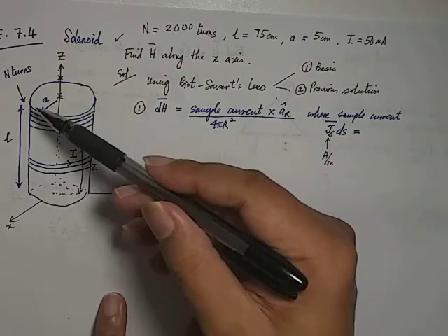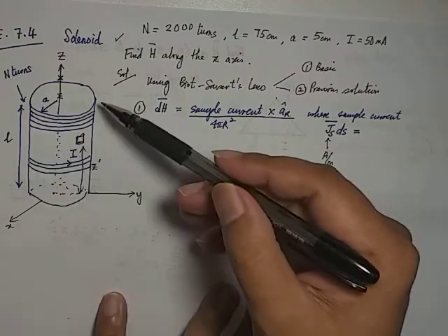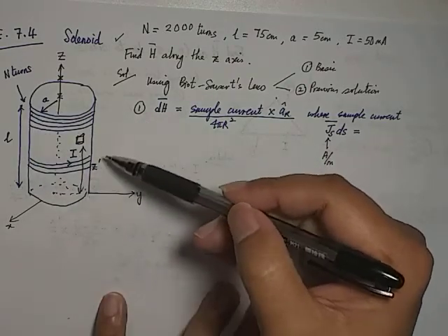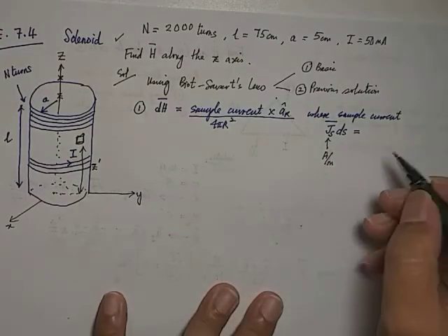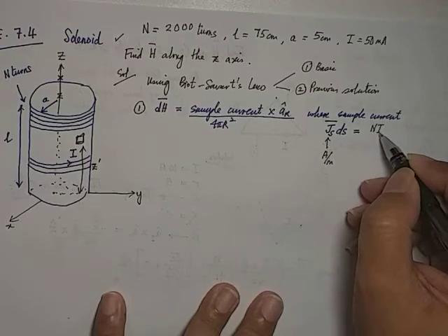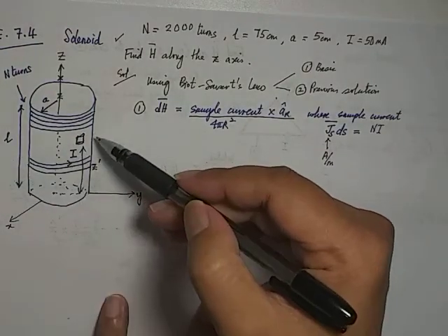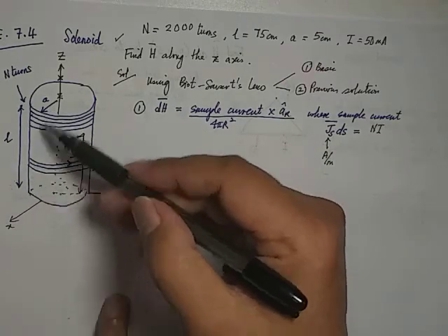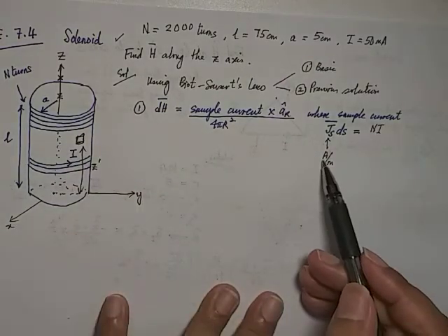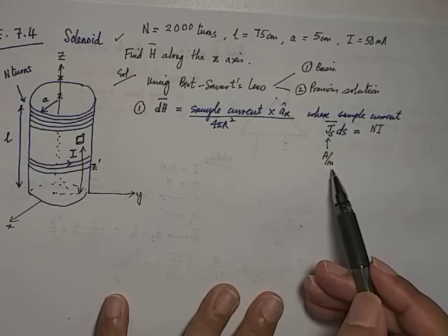So therefore I can see the total current coming out is N multiplied with I. The total current going into is N also multiplied with I. So I'm going to say it's going to be NI. That should be the total current per side coming out from the paper, going into the paper. I can see that's referring to ampere, okay? And then meter, so therefore it must be divided by length.